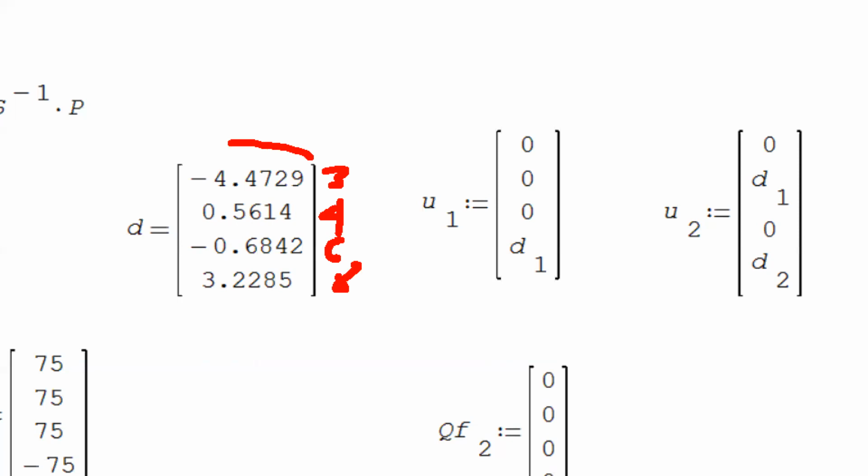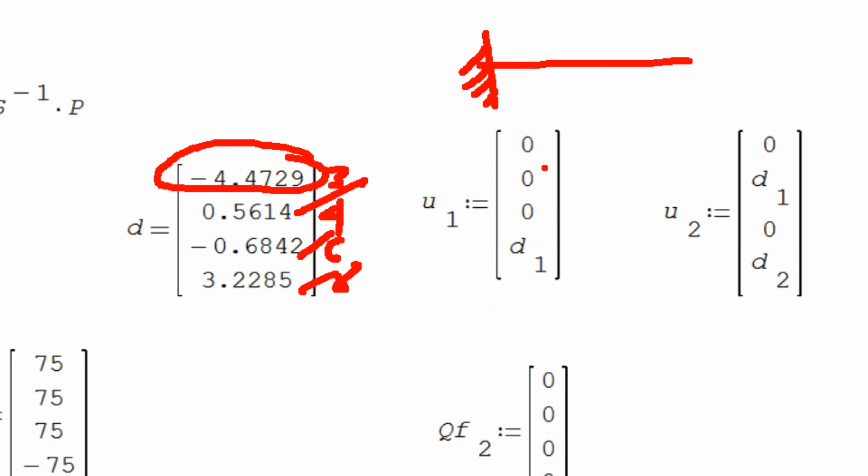That means this is a vertical displacement, and this is the rotation, rotation and rotation. So let's verify that in STAAD. And also, remember, we are fixed connected on member 1, so U1 is correct, 0, 0.